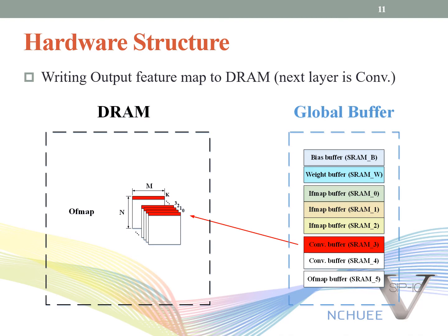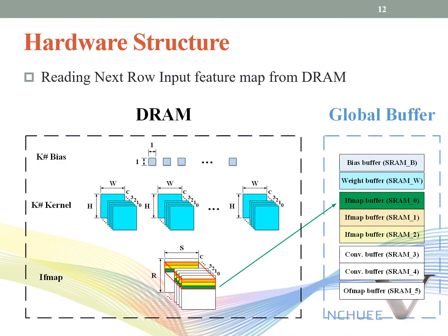Once all three rows are done, the value stored in SRAM3 can be transmitted directly to DRAM continuously. The next row of data will replace SRAM0, in order to decrease the transmission times by reusing SRAM1 and SRAM2 data. Respectively, next SRAM1 is replaced, then SRAM2 is replaced.